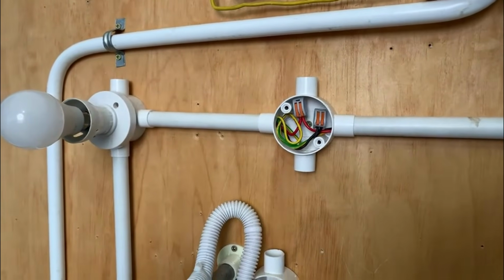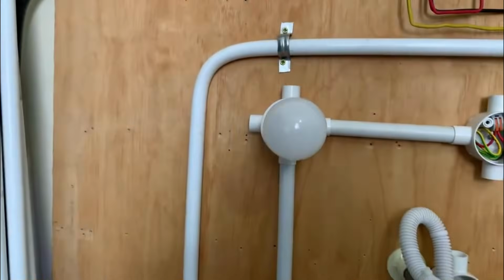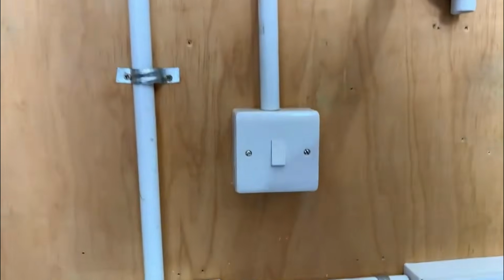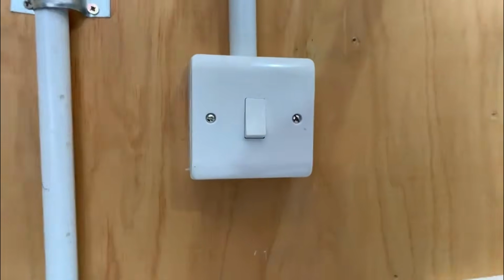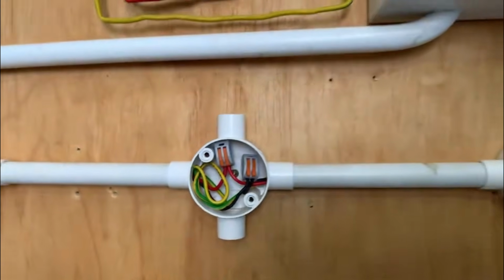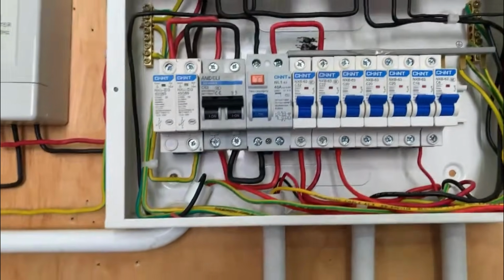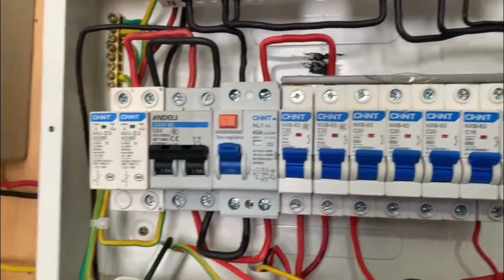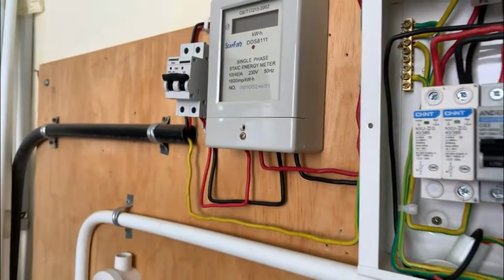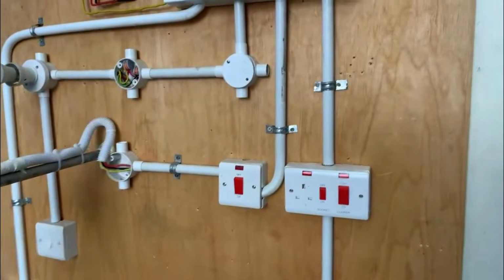But if it occurs, you find that it is in the fixtures, the bulb holders, or at the connection where you have that lighting, probably the switches, or if there's a loose connection at the JB junction box right there, or any looping or termination box, right? So you're going to talk about that, especially at the meter box. If there's a loose connection, definitely you are going to have it rough.